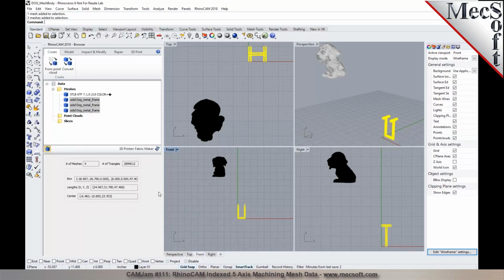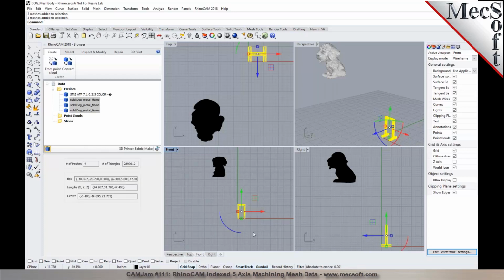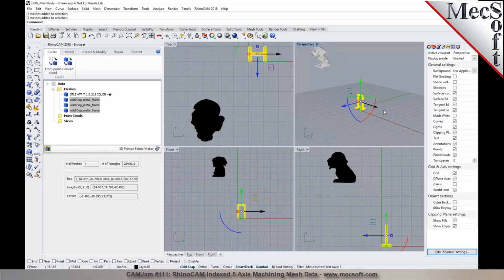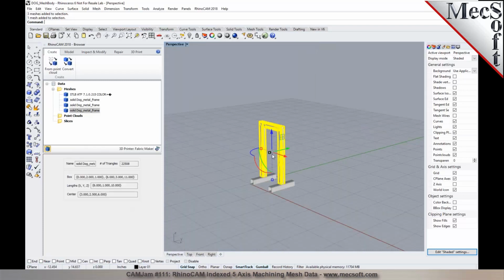Okay. So right now I can select this in here. I can use the tools in Rhino and I can flip this over by 180. How did you do that? So if you select the object, there's what is called a gumball in Rhino, which is a graphical manipulation tool. So when you highlight any object, it'll display the gumball if you activate the gumball.